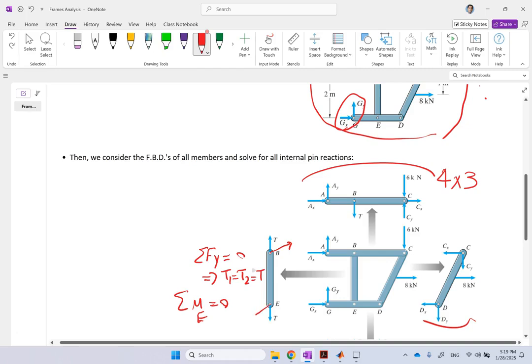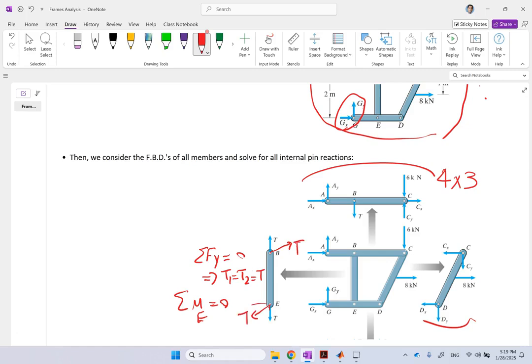And basically that is to say there are 2 components, right? Because there is a horizontal, there is a vertical. Now, could these T's be like this? No, because they create a couple here. And that will make sum of the moment about Z not be equal to 0. The only scenario for it to be 0 is if you connect E and B together, these T's should be along that line. So you see 2 of the equations are already used in the 2-force member thing.